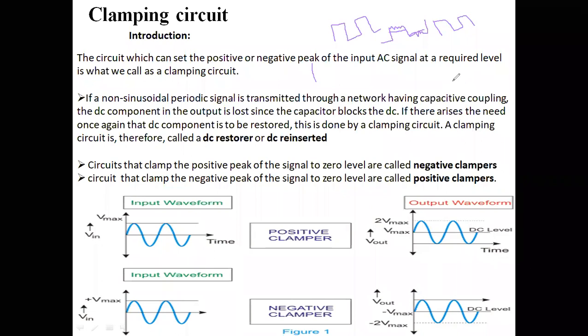At the input of the amplifier there should be some limited voltage. Suppose our amplifier works for only 5 volts. If our input has 10 volts, then we will clip the 5 volts. That means if the input has 10 volts peak to peak, then our amplifier requires only 5 volts peak to peak. Then the part above 5 volts is going to be clipped out.